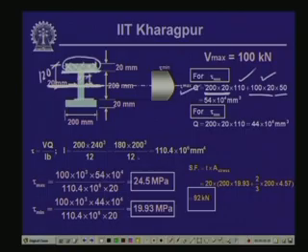So, Q for this particular section, where the shearing stress is maximum, for tau max, is this value, and if you compute it, it comes out as 54 into 10 to the power 4 millimeter cube. Now, Q is A y bar. The unit of A is millimeter square and y bar is millimeter, hence this is millimeter cube.